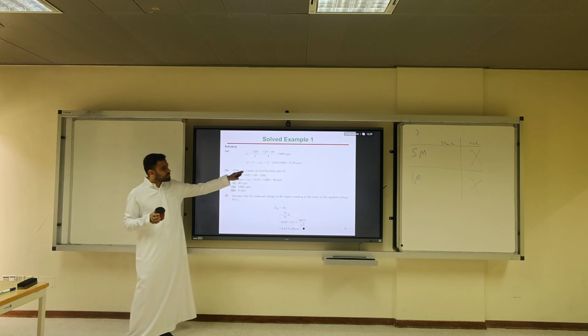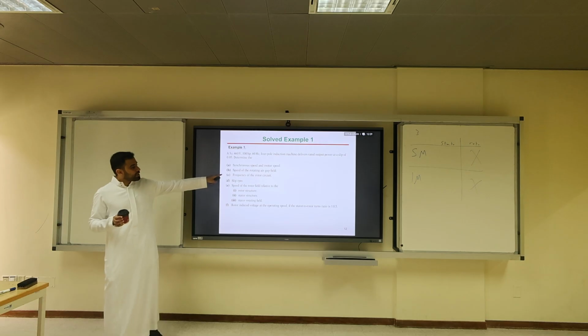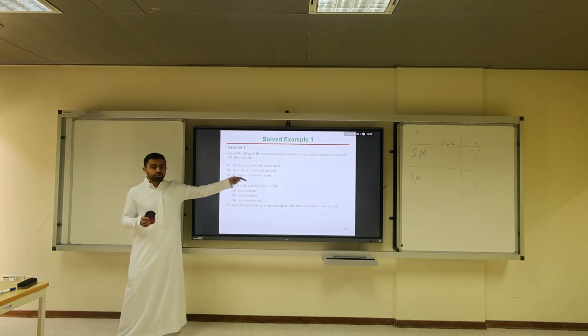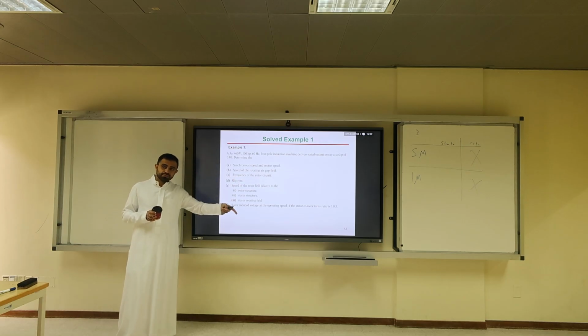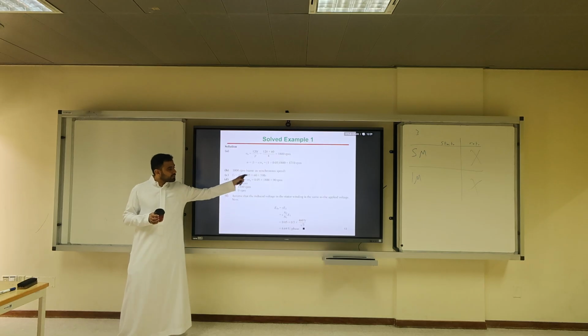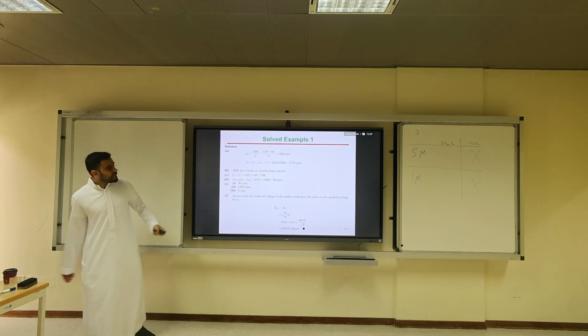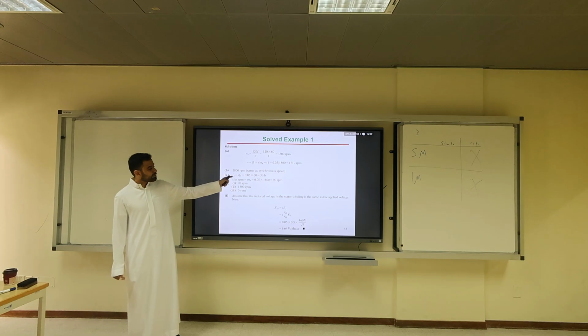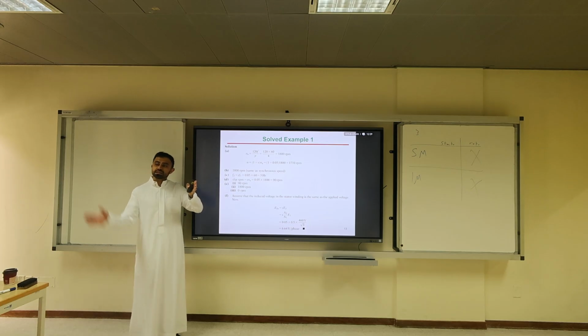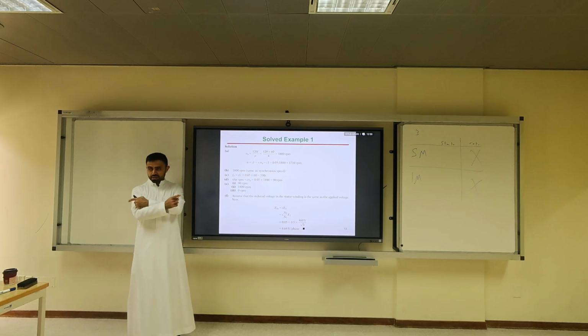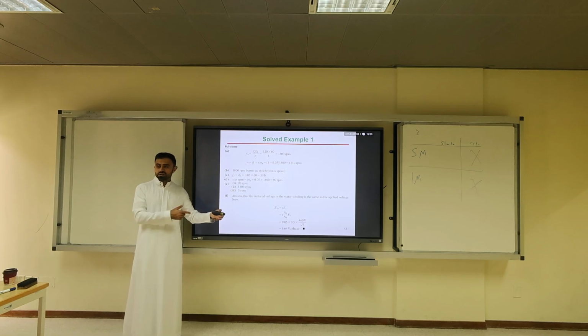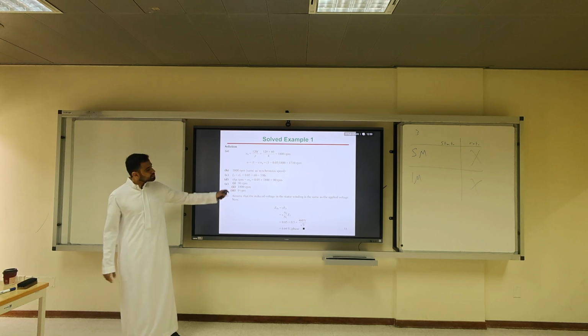So it is 1800. Third part, what is the frequency of the rotor? It's S times F, which is 0.05 times 60, 3 Hertz. Keep in mind that if the slip changes, meaning the speed has already changed, the frequency will change, and vice versa. So one way to control is, if I can, with the slip ring, change the frequency of the rotor bars, I can change the speed the other way.